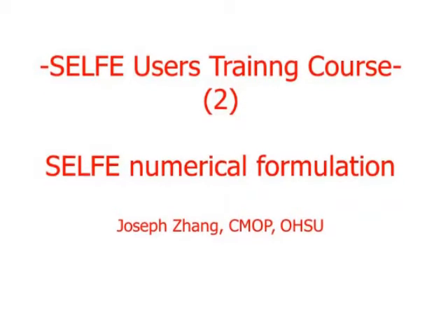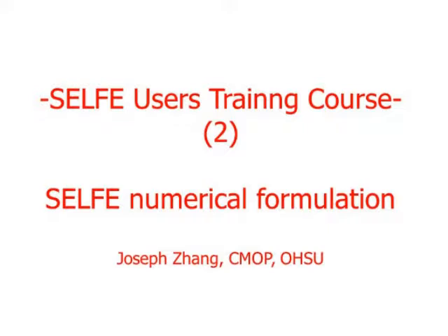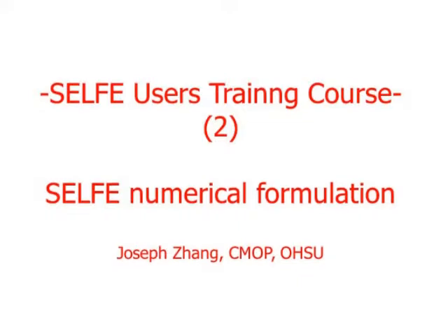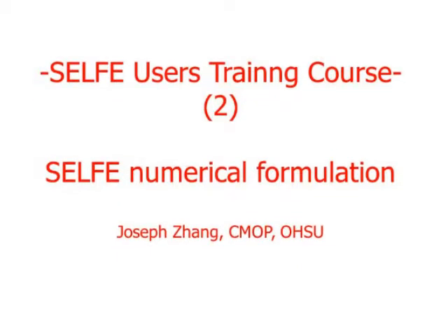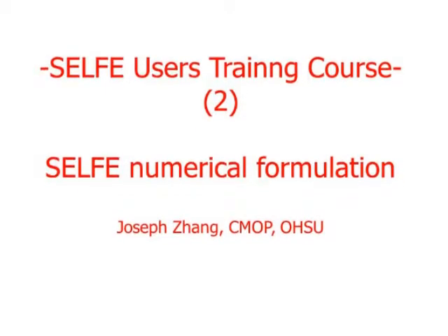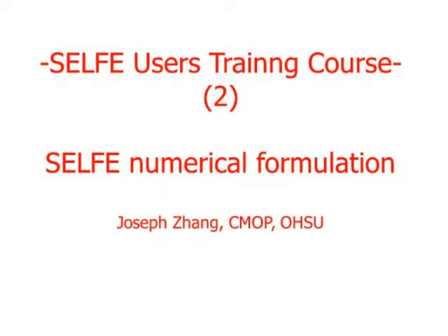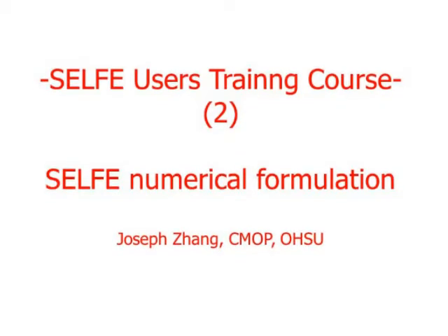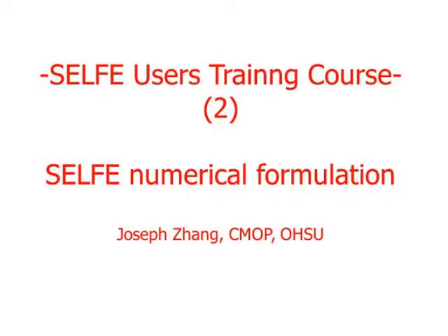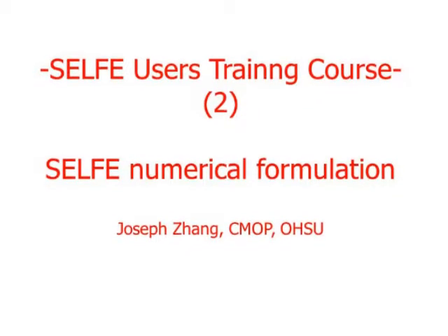Another thing is that we do not transform the equations into S or sigma coordinates. We solve everything in the original Z space, so that simplifies the implementation of the SZ hybrid coordinate system. In many parts of the model, you need to do 3D interpolation in space, and we allow users to do that interpolation either along S or Z planes. The bottom two pictures show you the two interpolation modes.